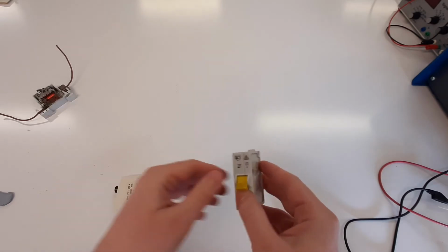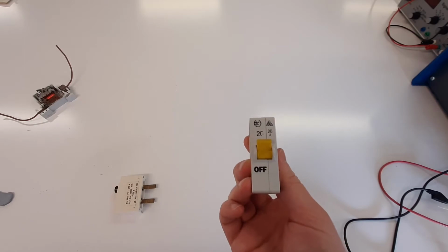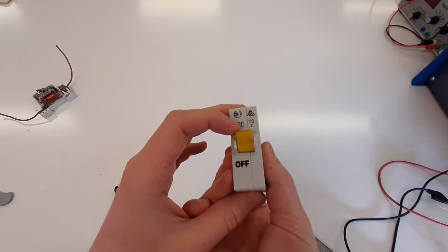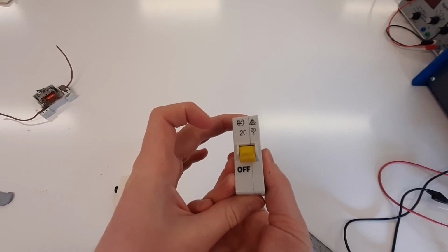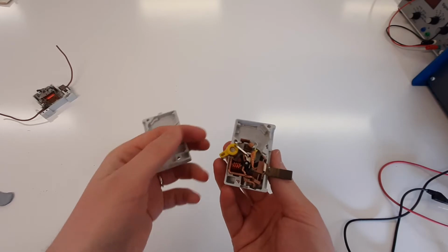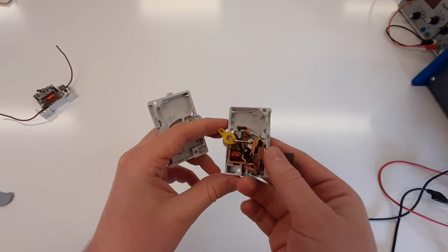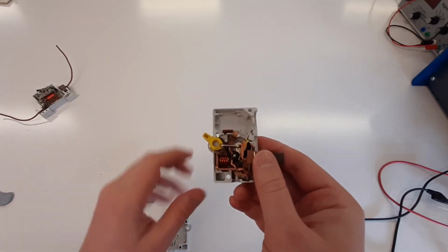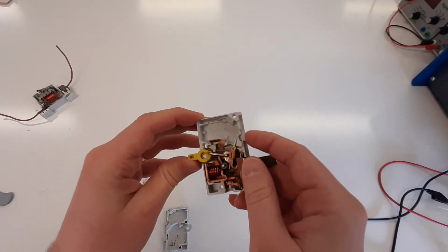This is a more modern one, and you probably see this one more often. Switch goes up, and there you go. It's plugged into exactly the same sort of thing, with a loss of contact there. And when there is a surge of current, it drops down into the off position. And there you go. So this is the inside of it, and you can see it's rather complicated. But we have these contacts here and here, and when there is a surge of current, that flicks back into that place, and we break our connection.